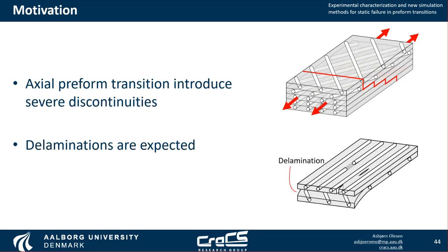And a particularly critical thing that is a worry here is that a delamination might initiate in one discontinuity, but then grow as a zipper effect across the whole transition and thus fail very quickly the entire thickness of the laminate.